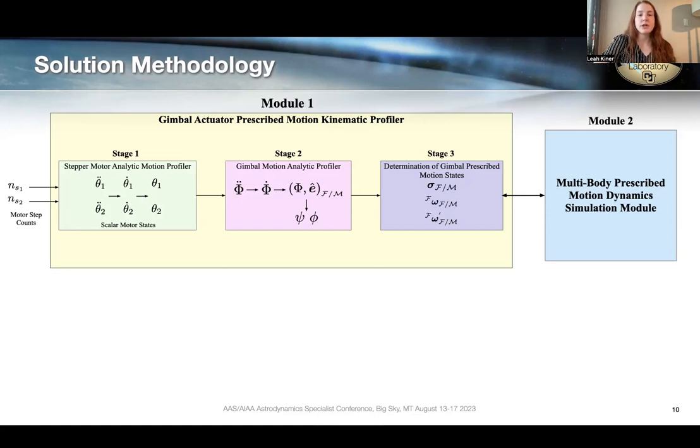And then we are going to analytically profile first the stepper motor states, and then using that information, we will analytically profile the gimbal's motion. And then with our gimbal profiled motion, we can then determine the rotational prescribed motion states of interest here, our sigma, our angular velocity, and our angular acceleration of the gimbal relative to the mount frame.